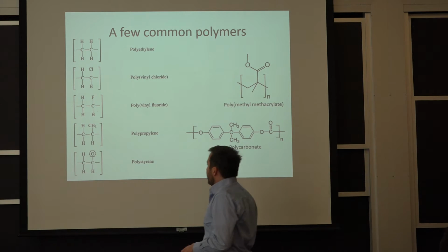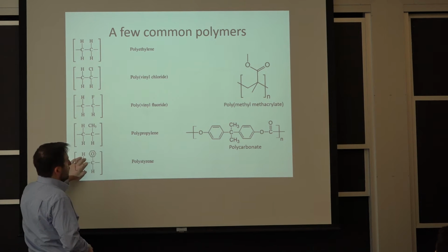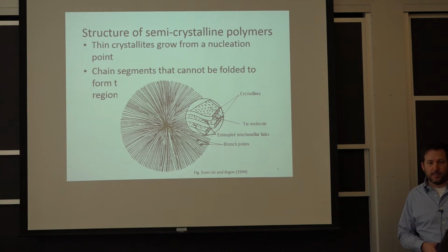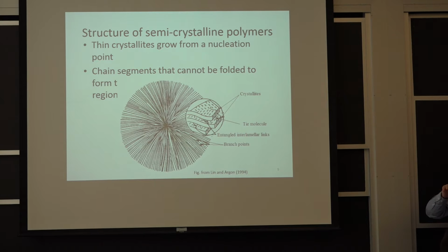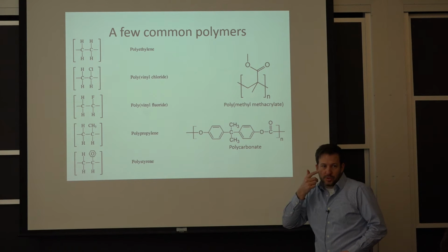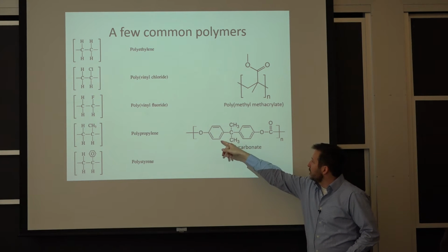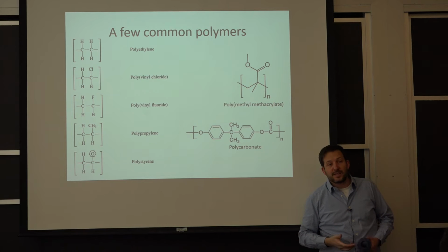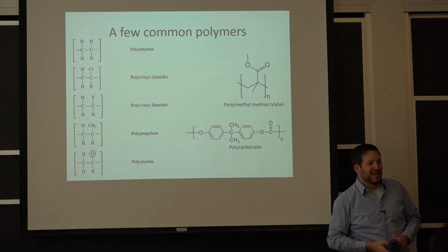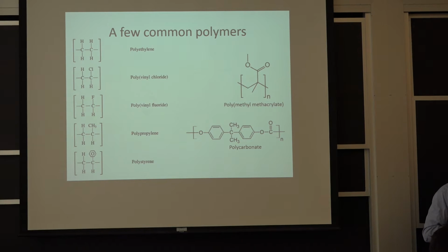So if you're the polystyrene here, it's going to be pretty hard to turn into a network of little layers of crystals with amorphous zone. It's because it's harder to make that movement. So on the extreme, just going back one more time here, the polycarbonate, what we use for glasses, you see it's got a much more complex molecular structure, and therefore it doesn't crystallize. And that's why it's transparent too. But all these things end up being related.